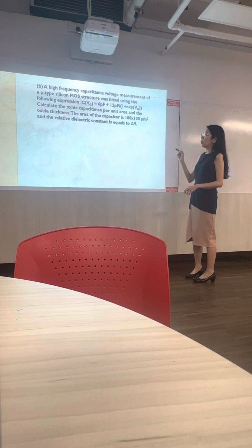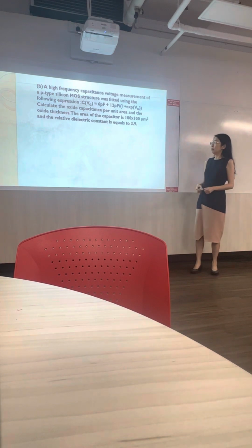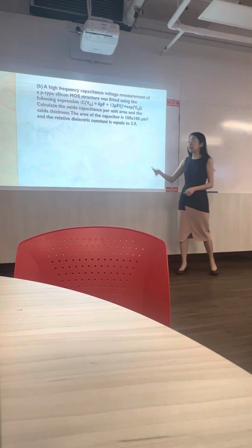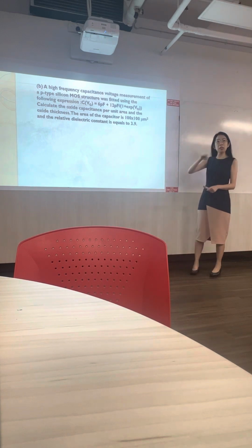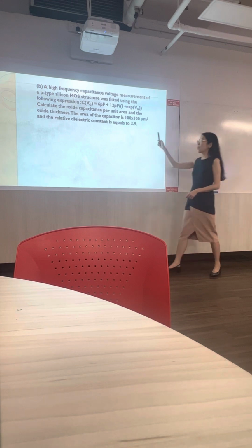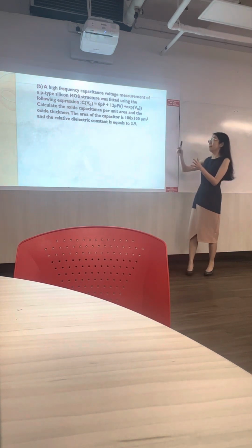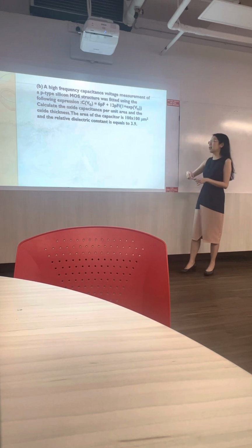Okay, so this second question is actually related to electrical capacitance measurement. Let's say an engineer did a high frequency voltage measurement. If you want, you can come to my lab, I can also show you how to do the measurement. We have a P substrate MOS structure, a test structure. You press the button, then you collect the high frequency capacitance.